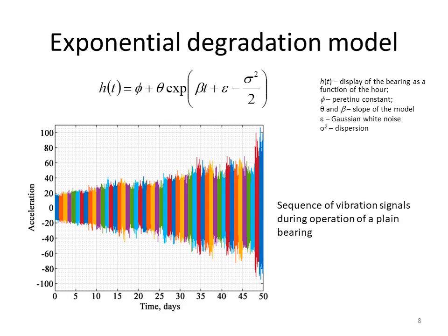Degradation models extrapolate past behavior to predict future behavior. This type of calculation is appropriate when determining the steady-state useful life of complex equipment. The degradation profile of the test components is used to statistically calculate the remaining time until the diagnostic indication reaches a certain degradation level agreed with the regulation.